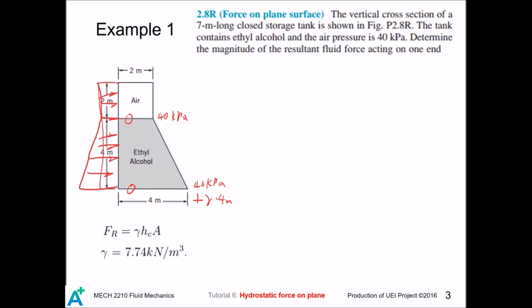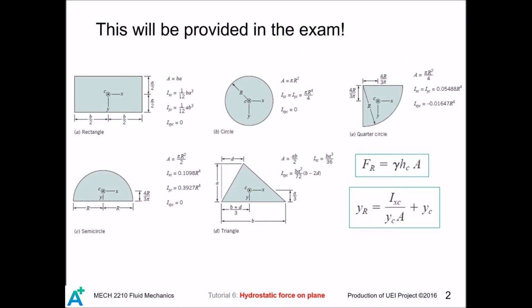So we may think that the air pressure is acting throughout the area, and we can break the force into a hydrostatic component and an air pressure component. So let's calculate the hydrostatic component of the force with the formula that I put down here. But there is a problem. There is no trapezium in this table. How can we locate the center of the trapezium?